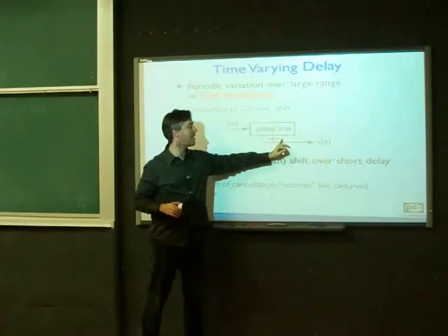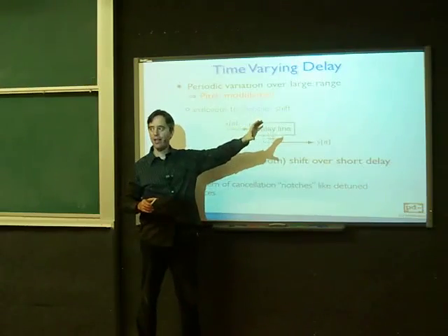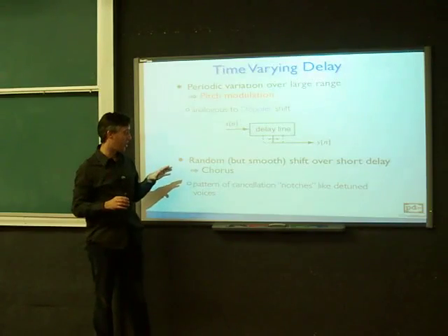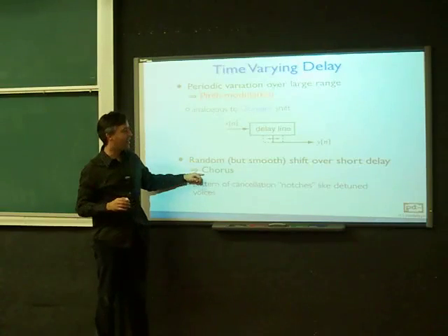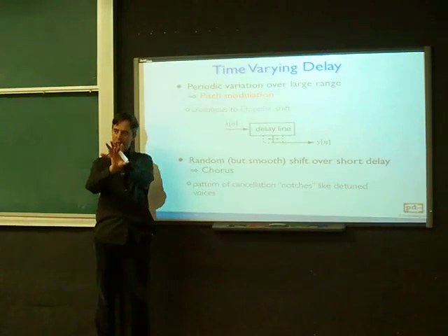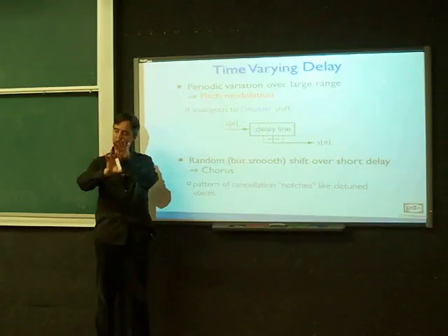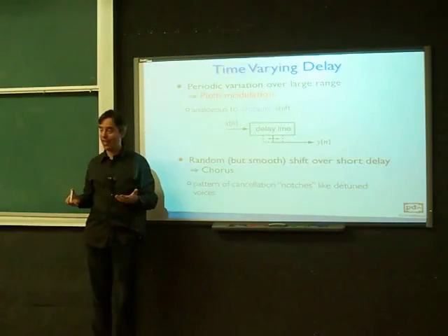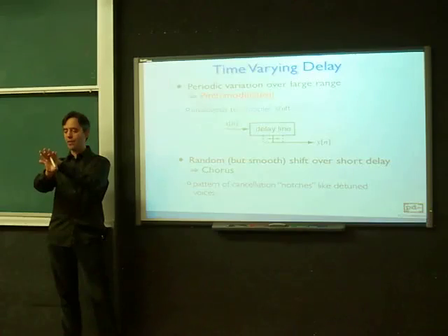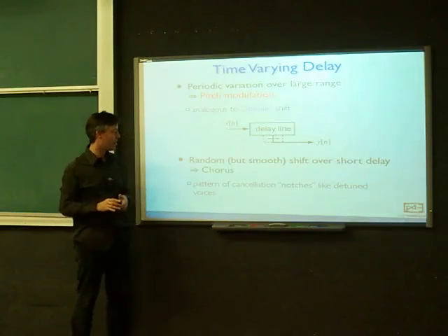So if you have a time-varying delay where you periodically increase and decrease, then you're getting this Doppler shift where it's pushing the pitch up and pushing the pitch down, and you can get a slight pitch shift. And then when you add that back into the original signal, because you've got slight changes in pitch, you can think of your signal as having harmonics shifting relative to one another, and occasionally they're cancelling out, and you get an effect which is very much like the sound of lots of people trying to sing the same note at the same time. They're almost on pitch, but there's a little cluster of harmonics around every point, which gives you the so-called chorus effect.